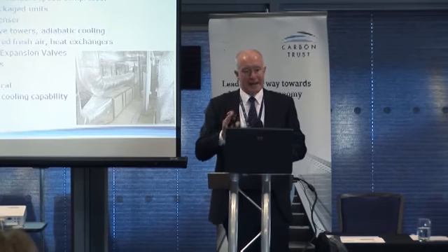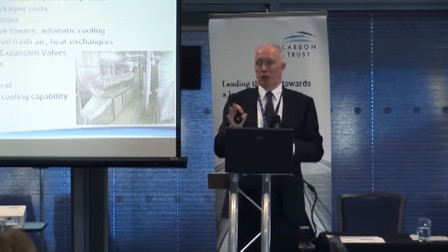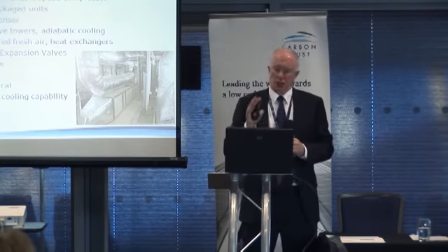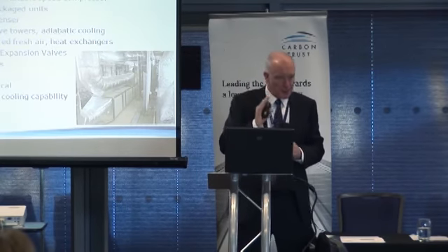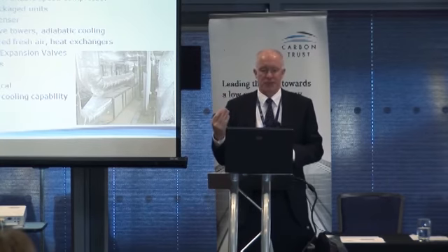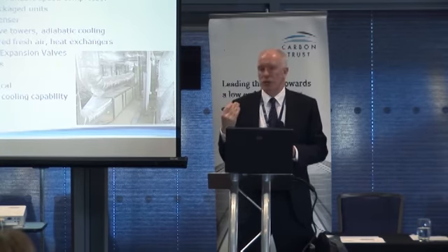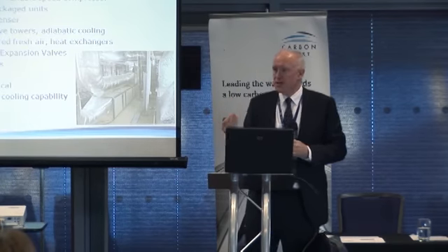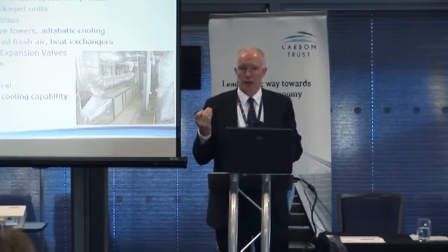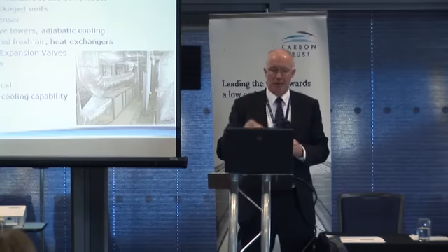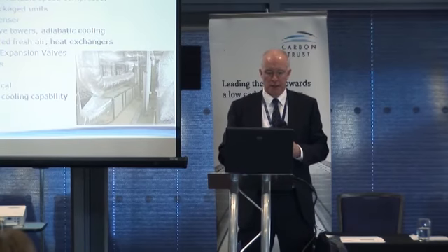I'm not going to go greatly into low carbon refrigeration, because I'd like you all to think about trying to avoid refrigeration as much as possible. But if you have got refrigeration, lots of things could be done: converting from direct expansion to water-cooled systems, modular systems, variable speed drive compressors. Lots of high-efficiency packaged units are now available, turbo chillers, etc. Free cooling to the condensers, so that chillers give free cooling, is available. So if you are looking at replacing any kit, then look at energy-efficient options when you're doing that.